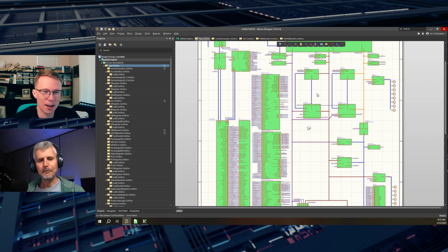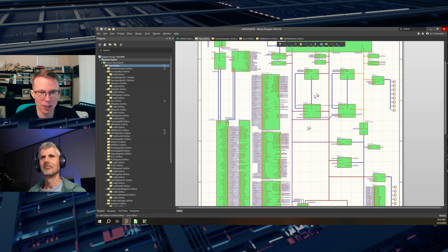The fun story there is that I actually had part of the layout already completely done before I thought, maybe I should take a step back and build the program counter, because this is going to be a very expensive board. It turned out the program counter worked and the carry propagate worked, which was really what I was worried about. I was concerned that there would be some gate threshold issues, where the carry would propagate partway and then stop, or some timing issue. But it actually worked fine. Yeah, I guess also because you've got a 2-phase clock here.